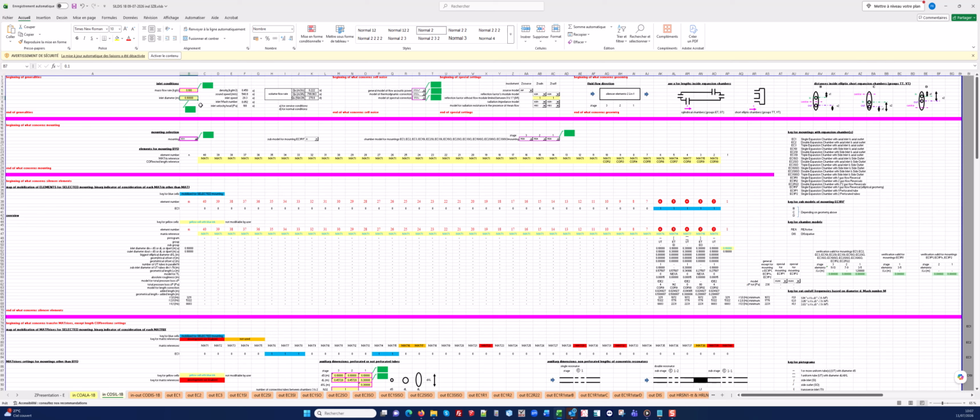We can enter the inlet diameter of the silencer, 100 mm here, and we can select models relating to the self-noise here. A general model of flow acoustic power among a drop-down menu list, a model for thermodynamic correction here, a model for spectral correction here.